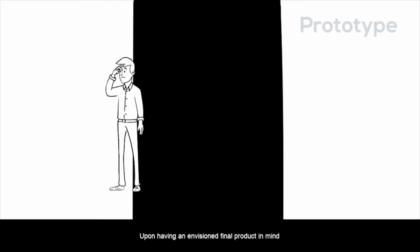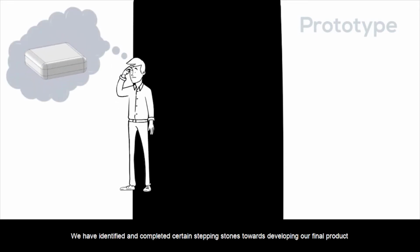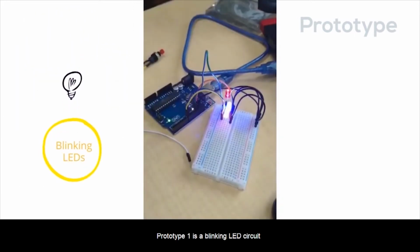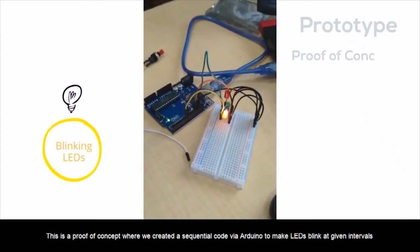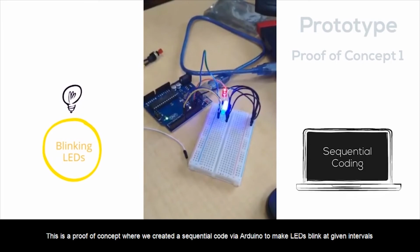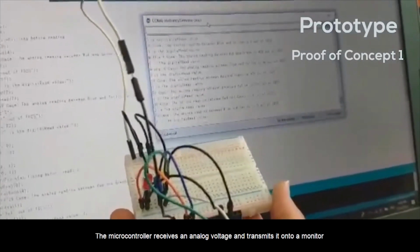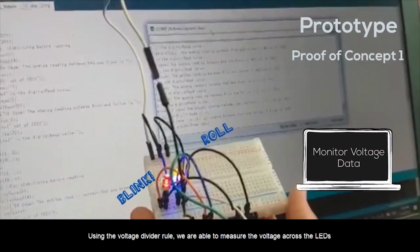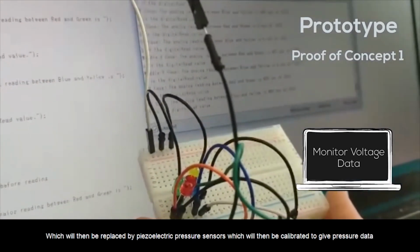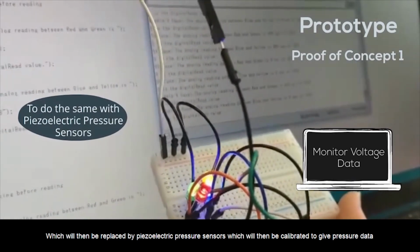Upon having an envisioned final product in mind, we have identified and completed certain stepping stones towards developing our final product. Prototype 1 is a blinking LED circuit. This is a proof of concept where we created a sequential code via Arduino to make the LEDs blink at given intervals. The microcontroller receives an analog voltage and transmits it onto a monitor. Using the voltage divider rule, we are able to measure the voltage across the LEDs, which would then be replaced by piezoelectric pressure sensors, which would then be calibrated to give pressure data.